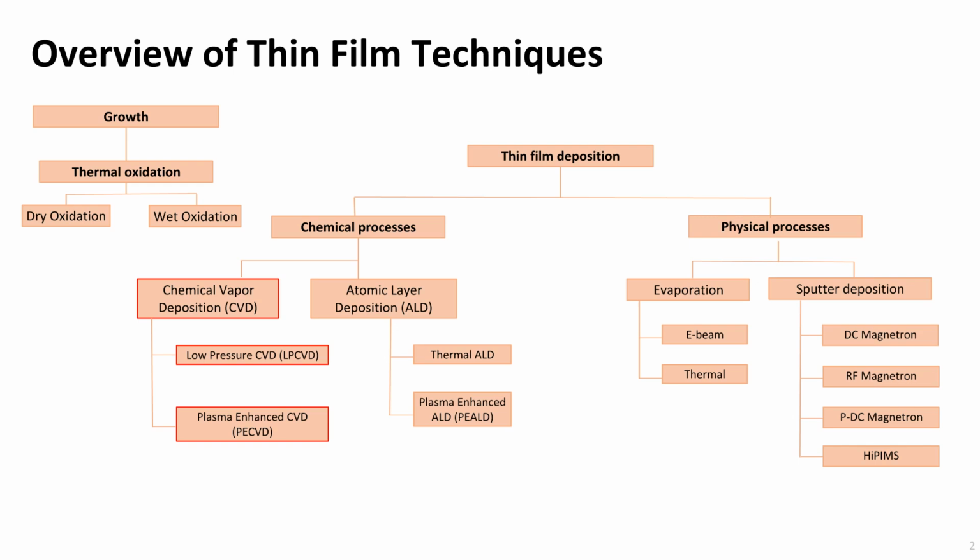and gas concentration. CVD encompasses a wide range of techniques, each with its unique characteristics and applications. Based on operating pressure, CVD processes can be divided into high vacuum, low pressure, atmospheric, and high pressure CVD. Or based on physical characteristics of the vapor, or the type of substrate heating. Special types include the plasma-enhanced CVD, atomic layer deposition, or metal-organic CVD. In this lecture, we will only discuss low-pressure CVD and plasma-enhanced CVD.